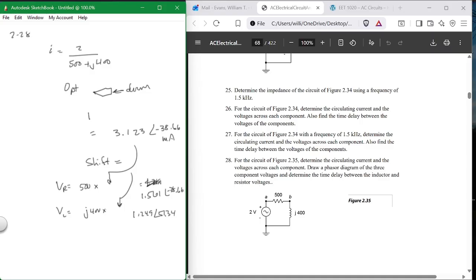Voltage divider is your best friend because you can use it for all kinds of things. And it's 1 step, done. Okay? Voltage divider is useful for a lot of stuff. And if you don't think it is, it is. If you want to step down from a higher voltage to a lower voltage, it's one of the things you build. A voltage divider, 2 resistors. Make sure they're high enough so that what you're trying to step down doesn't affect it. You'll figure it out. You just use it again and again and again. It's useful, very useful. So anyway, that's number 28. Any questions so far?